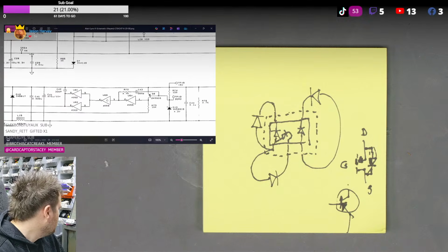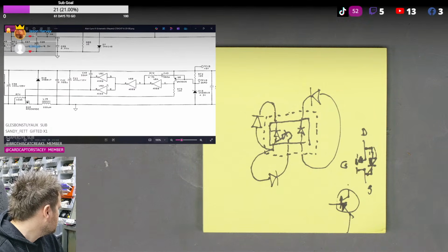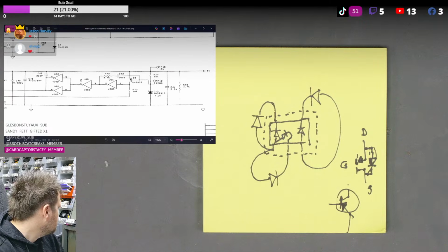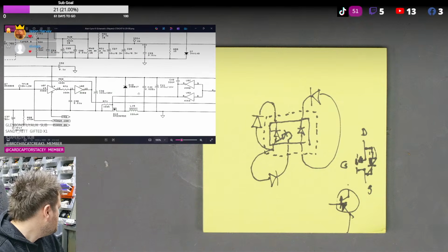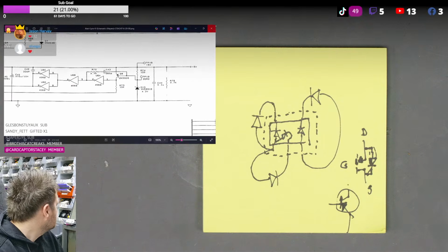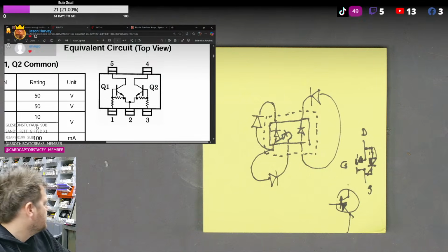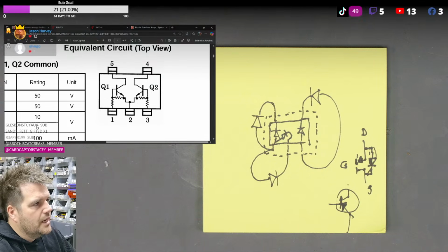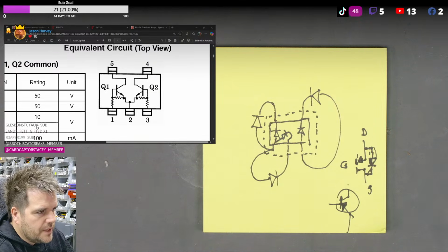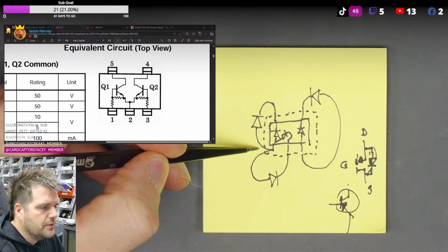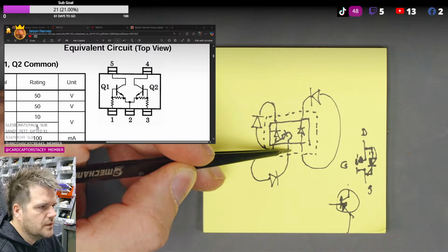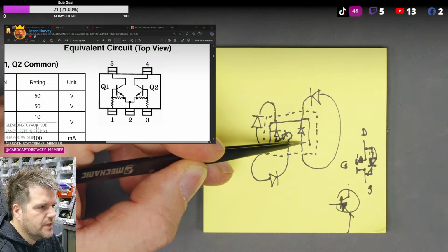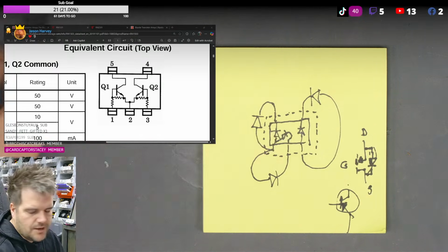Yeah, and this isn't an op amp. This is a hex inverter, basically. Yeah, so that doesn't give me any clues. But I don't think it's going to be an array, unless I'm staring at it and misinterpreting where the diodes are going. From pin 1 to 2 would go through here, but then you'd expect pin 3 to 2 to have a diode reading.